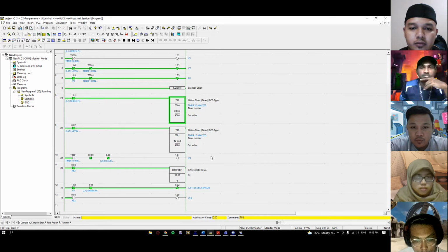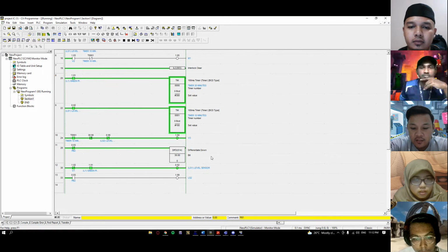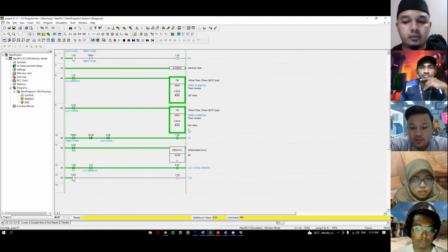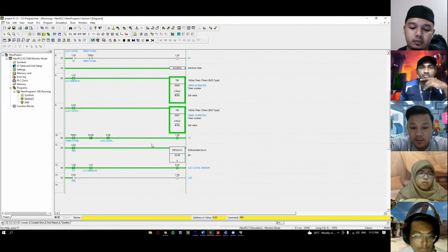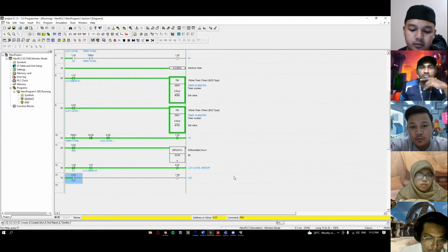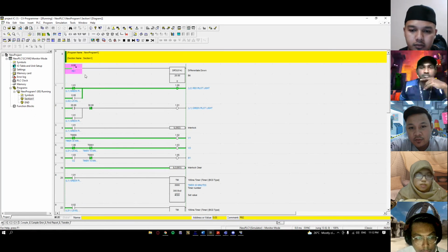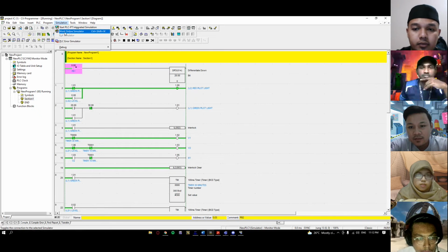We use PB2 for emptying the tank. When we press and release PB2, it will turn on LS2, turn off V3, and turn the red pilot light L2 back on. This condition is the initial condition for this setup. That's all for task 1. I will hand over to KUGAN for task 2.